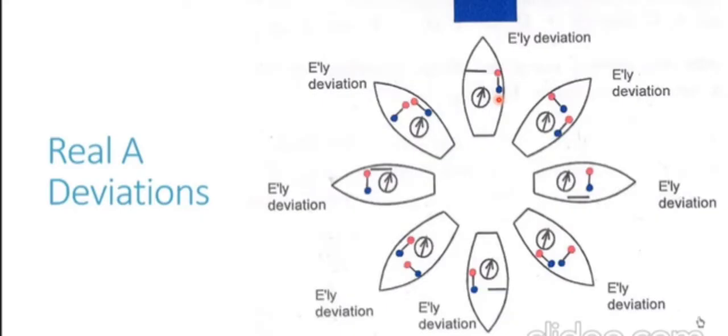And these lines of force going from south to north will be coming out from the forward end of the longitudinal. Since they are coming out of the forward end, the forward end of the longitudinal acquires red polarity. So this is the reason why you see in the diagram the aft end of the longitudinal has blue polarity and the forward end has red polarity. So we now understand the different poles generated on the fore and aft longitudinal.